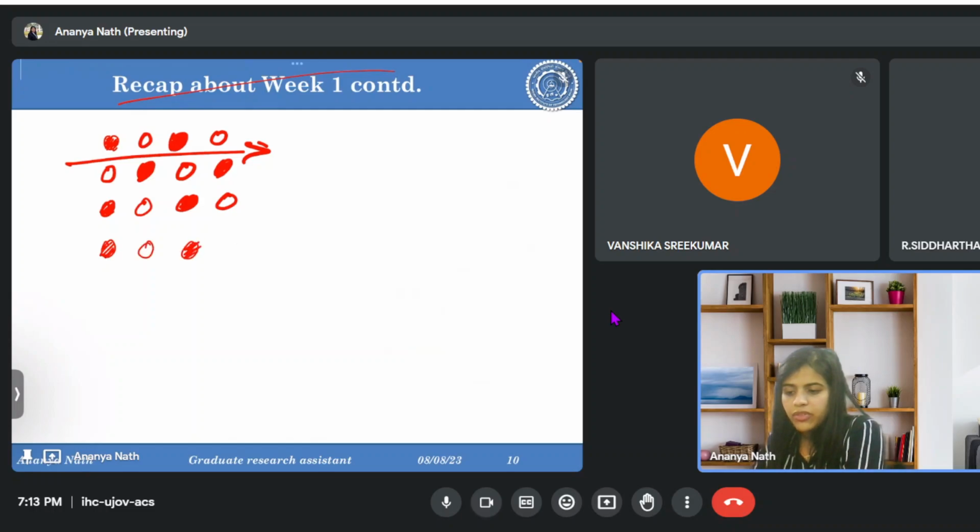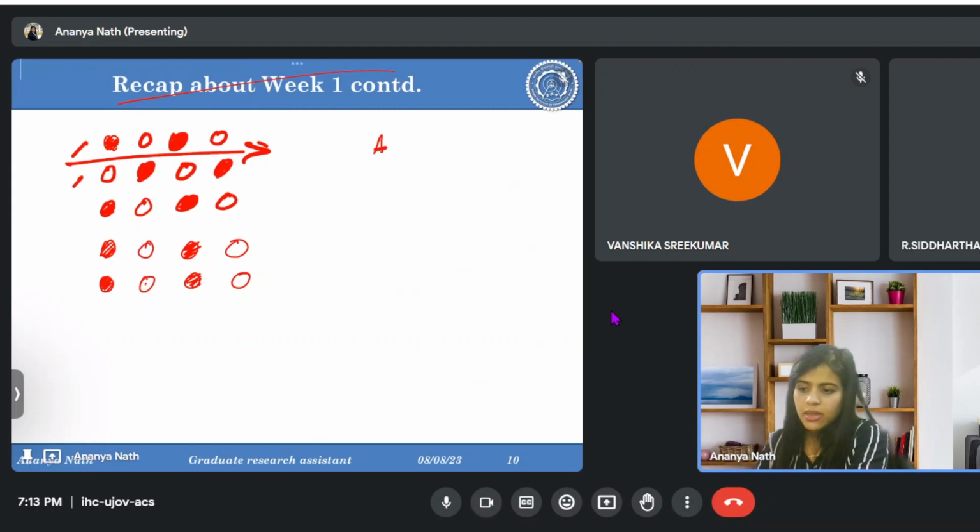Before, the opposite atoms were facing each other, but due to one step movement of the dislocation, this will be the next scenario where similar type of metals or atoms are facing each other. Always remember, if there are two types of metals, A and B, where B is the solute atom, the energy of this arrangement will always be higher than this, the energy of the system.